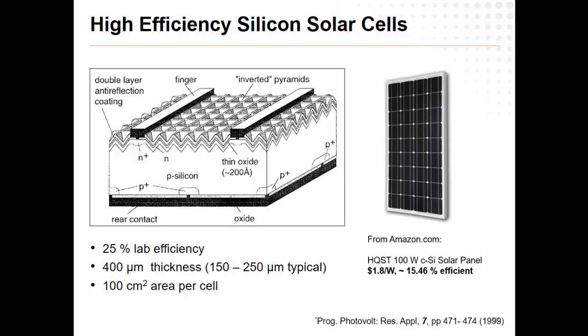That's probably where they get these numbers from: they actually have special lamps that are calibrated to that AM 1.5 spectrum. They stick the cell underneath and measure its efficiency using that. So in principle, it's rated for 100 watts. But if it's a hot day in Arizona, you might get 120 or 150 out of it. It's a little hand wavy, but you have to standardize this stuff somehow.